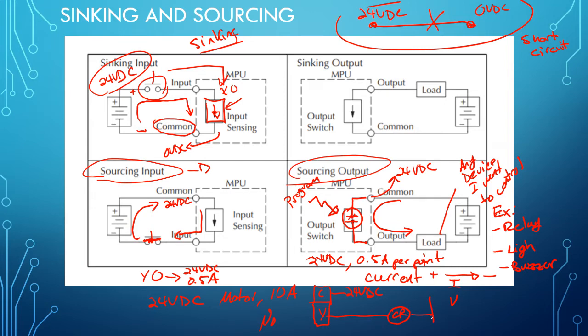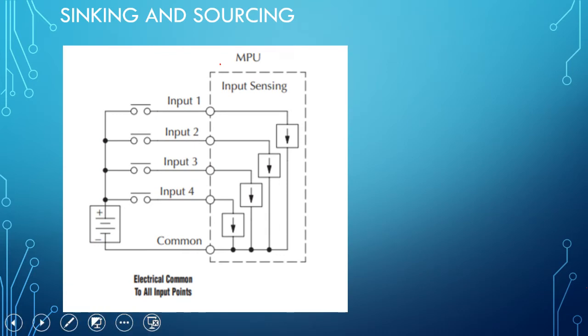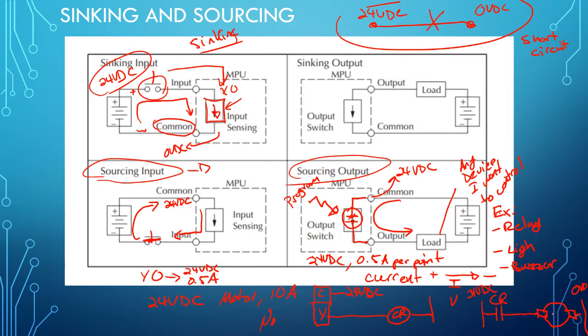The control relay has a set of contacts that is going to turn on 24 volts DC, 0 volts DC, and you're going to turn on the motor. And this contact is rated for, let's say, 12 amps. Give it a little bit more just in case. So you can provide that amount of current to the motor.